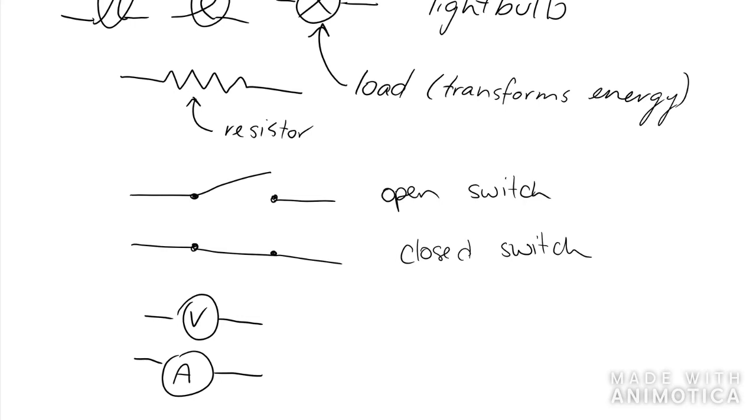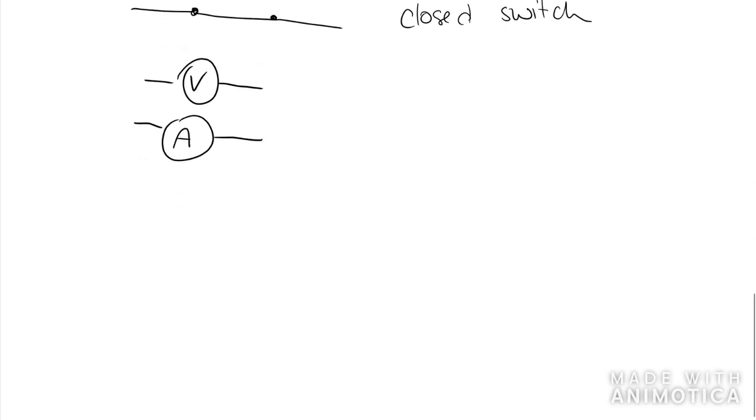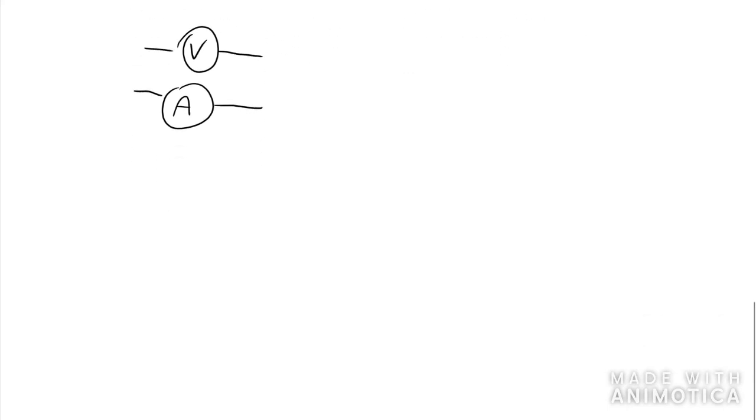This week, you're going to be practicing drawing your circuits. Again, you have to make sure that they're closed circuits, so we have a complete circuit that it can travel around. You also have to make sure that you don't have something called a short circuit. So let's say that we are going to do 2 cells with an open switch and a light bulb.